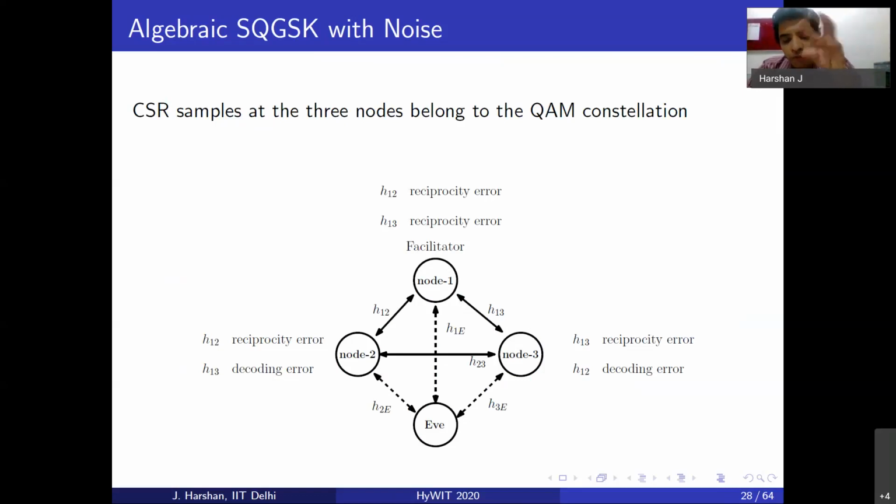Right now, we haven't seen how to improve these noise levels at this stage, especially given that there is no room for applying any coding across time or space, because all these operations are going to happen quickly in the protocol with just about 4 channel uses, right? If we constrain ourselves to these 4 channel uses, there is not much room apart from ensuring that the minimum distance properties of the two-dimensional constellation are maximized. Maybe instead of a QAM, at most I could use a hex because of its distance properties, but essentially that's it. I can't do more than that unless I am allowed to use additional time slots to code across time or any other dimension.